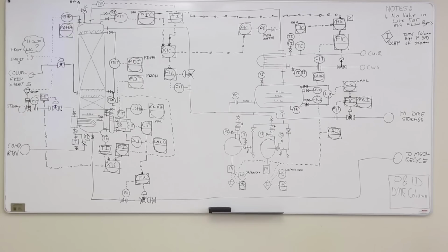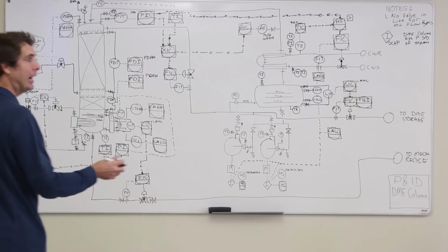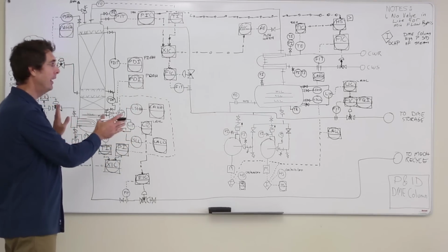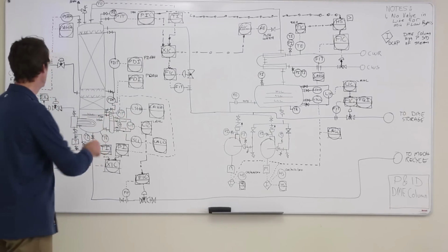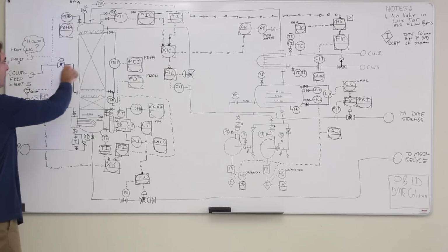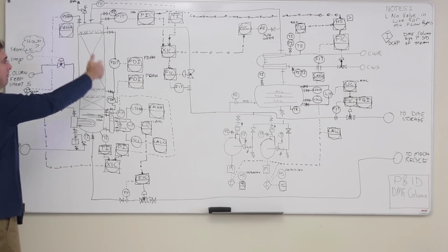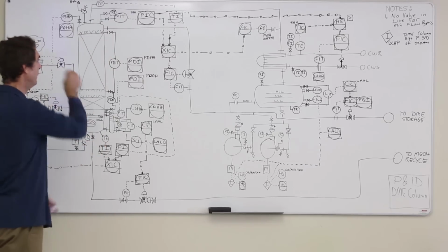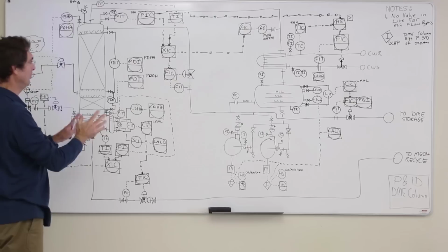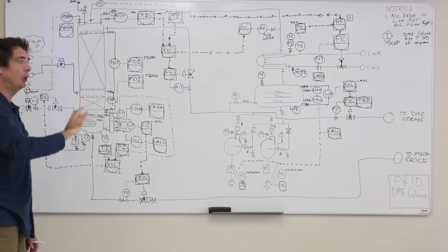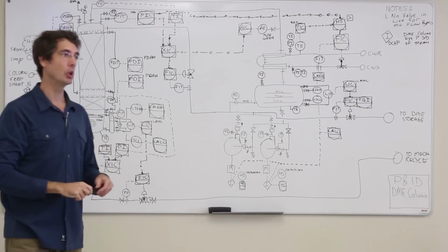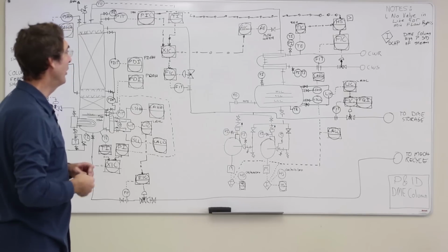When you look at it right now, it looks really scary, but if you build it up step by step, it's not as scary looking. If somebody were to drop a P&ID like this on your desk, the best way to go through it is to take a yellow marker and just start following the major flows through and yellow them off, very methodically, almost like you were going to build the P&ID, but you just follow it through. Don't get intimidated by the complexity of it right away. Find the major flows, find the major control loops, and then go back and look to see what other control loops are on there, or what other indicators.